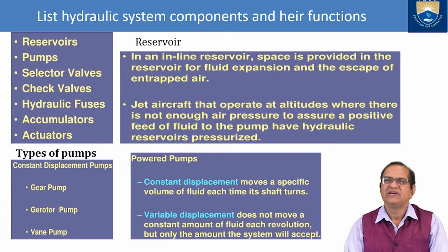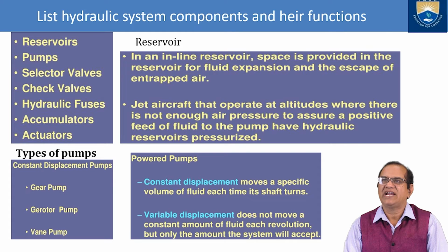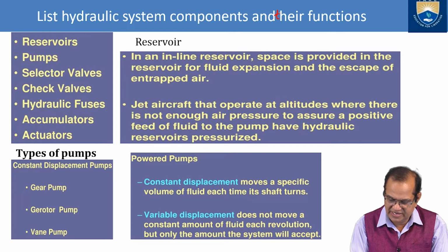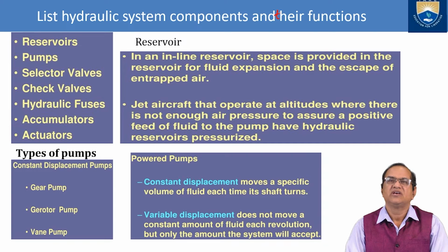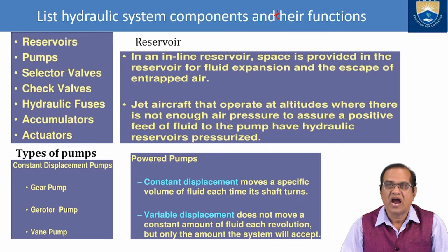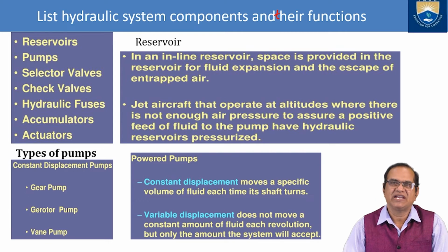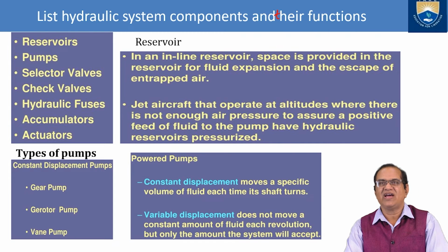List hydraulic system components and their functions. So we have the main components: reservoir, pumps, selector valves, check valves, hydraulic fuses, accumulators, and the actuators. So what is the reservoir?